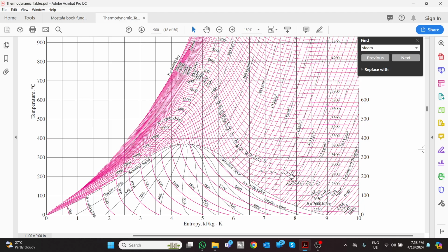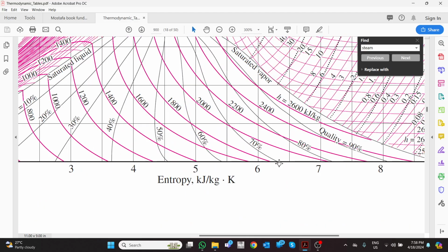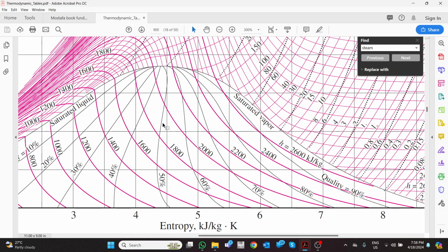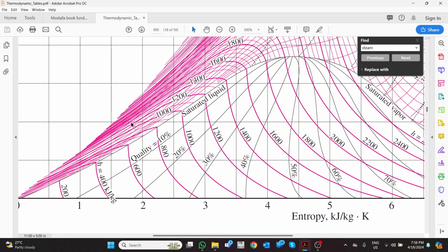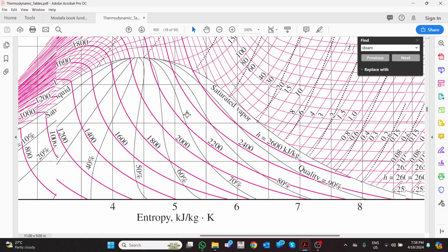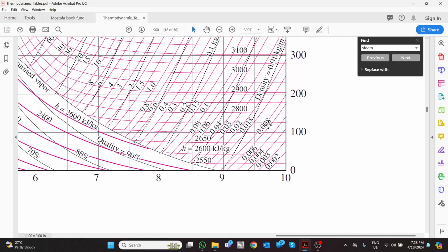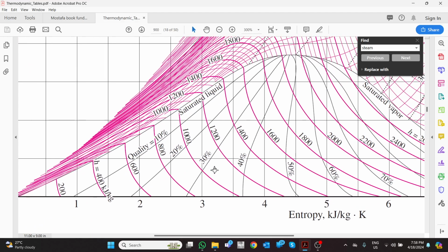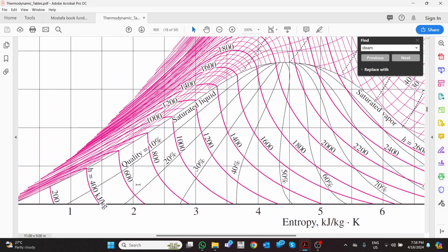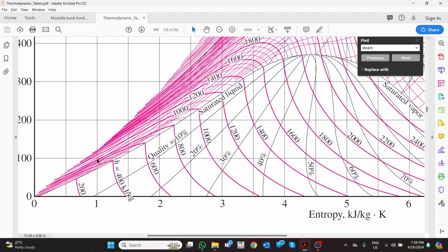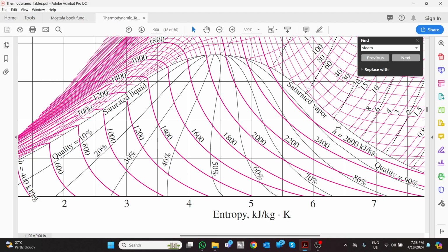So this is the steam, and this is the enthalpy, and here is a mixture. Here is a subcooled liquid, saturated liquid, saturated vapor, superheated vapor, and in case we are dealing with a steam turbine, you will have a bump here, increasing pressure like this till a point, then it will go straight, which is heating in the boiler at constant pressure.